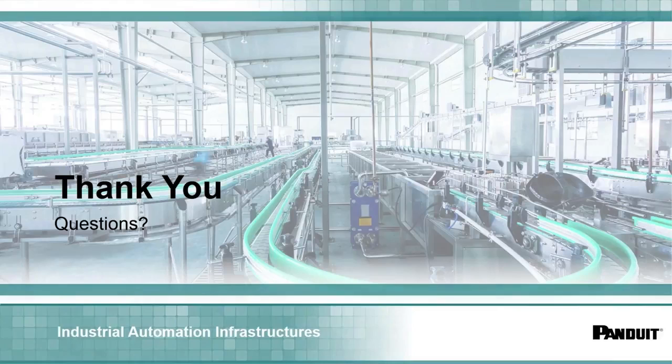And there is a cost and benefit that have to be weighed here. As you move from the medium to large size plant, we really recommend that not only do you not have the same devices connected to the enterprise on the same wire, but we actually suggest you put it on a different switch, or a lot of times in a separate cabinet. So we'll be segregating the business, the security, and the operational technology, the OT networks, onto their own network switches in a lot of cases.